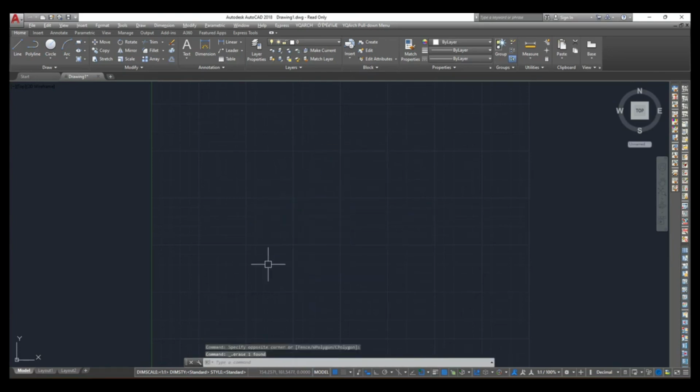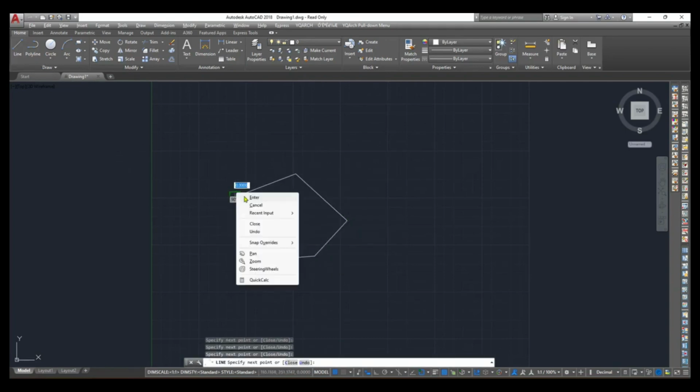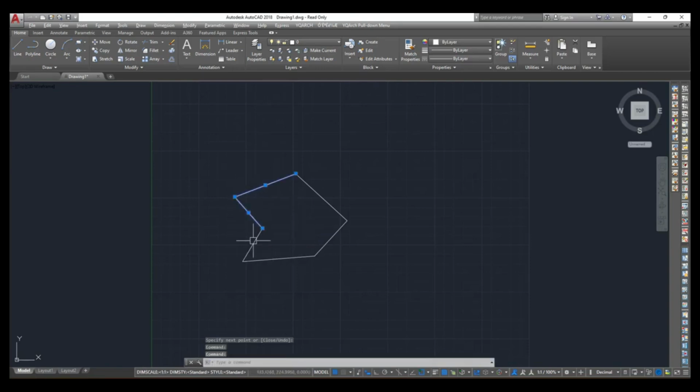The next one is region. In order to implement the region, I just draw the geometry by using the line command. As you know, this is done with the help of line command. That is nothing but single entity. So in order to combine it and make one whole geometry, I am going to use the region. For that, go to the draw panel, expand it and take the region and select whole object and enter, so that it become one geometry.